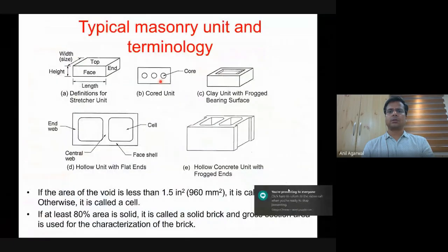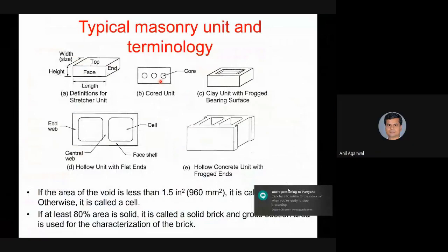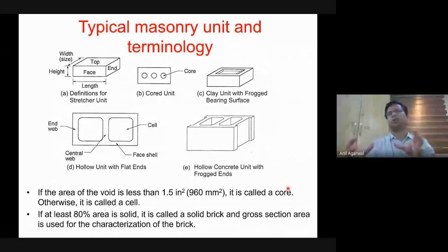Often you have a brick thickness, and for that thickness you don't want to reduce the size of the brick, but if I make a completely solid brick of that size, then it will be too heavy, and really I don't have a very high strength requirement. Sometimes if you cut cores from inside, you remove some material, and that still gives you large dimensions but with reduced net overall density, which may be good for you. So that's why they cut the cores.